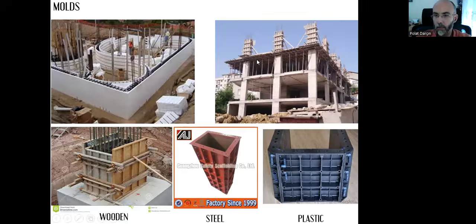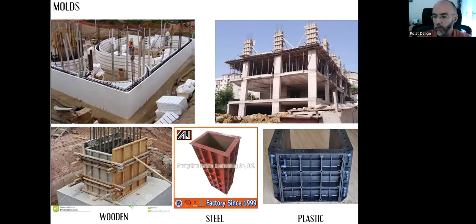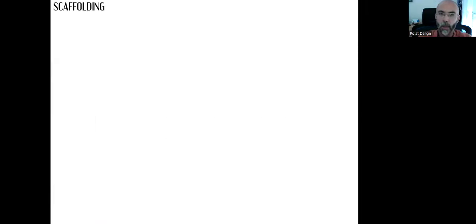As you can see, first they place these molds on this story to create these columns. Once the final set is over, the molds are removed and carried upstairs to create new columns, over and over again. So they need to be strong and durable enough to be reused.